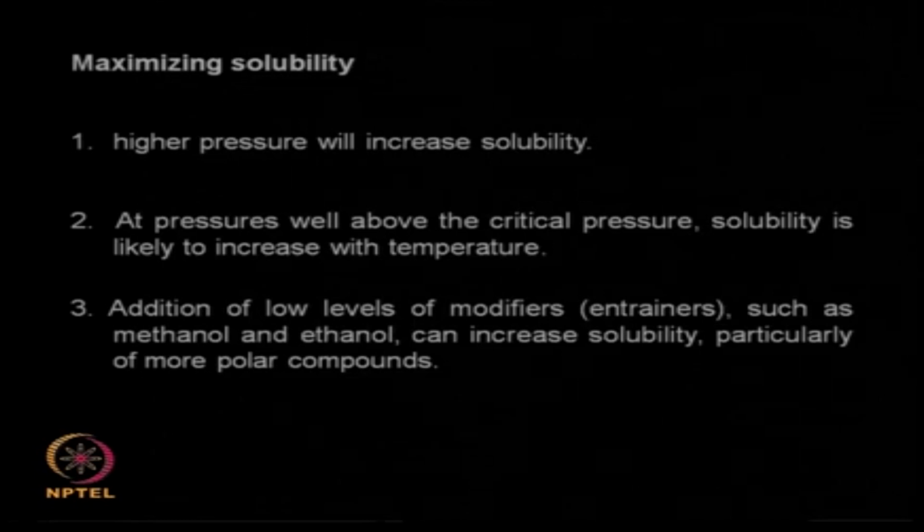How do you maximize solubility? So we can use higher pressure. When you use a higher pressure, solubility increases. At pressures well above critical pressure, solubility is likely to increase with temperature also. So if you are using very high pressure, then the supercritical CO2 temperature also may be very high.